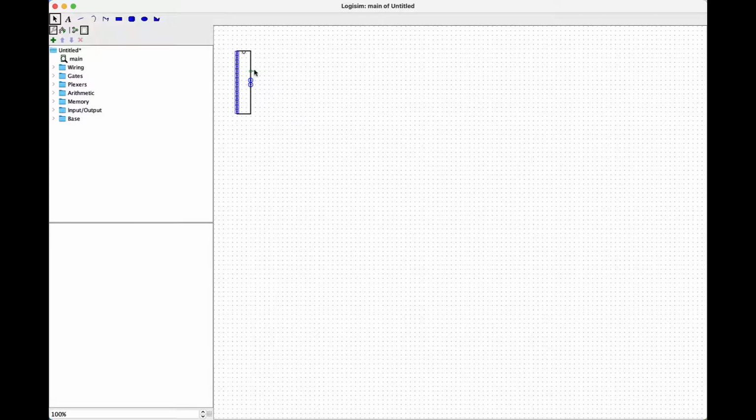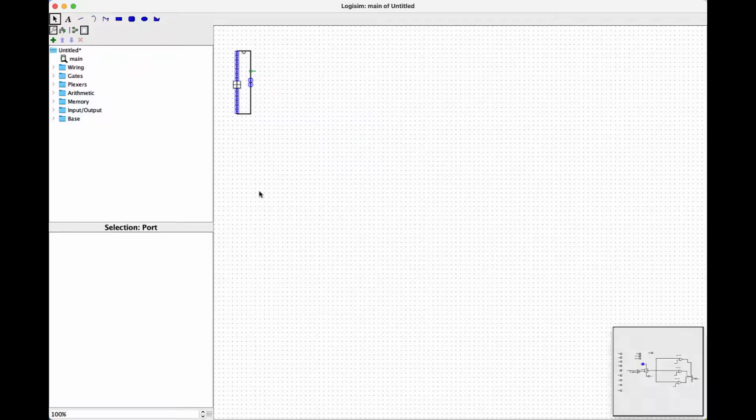and this is a directional guide right here, so it shows you which way this is rotated. You can also use this little U thing to show you the direction. And you can see that one is our C out output pin. And then we have all of our different input pins. Now you might want to rearrange them and make sure that they're in the right spot. Just make sure that you know which pin is which as you rearrange them and maybe label them.